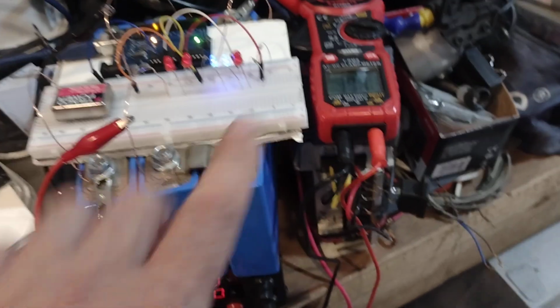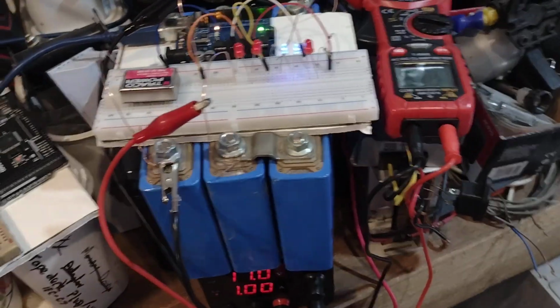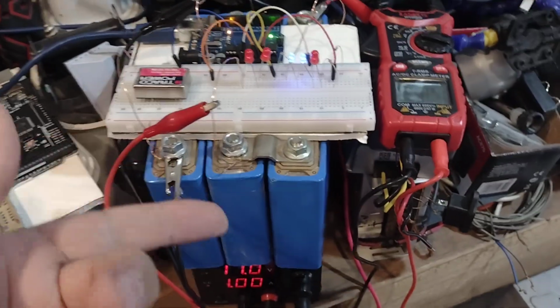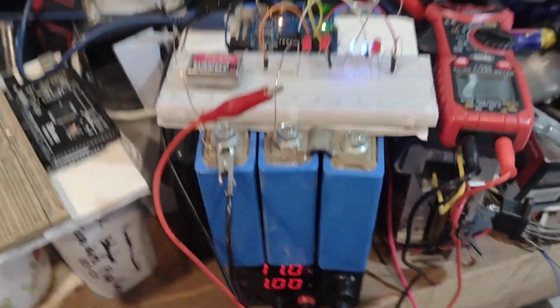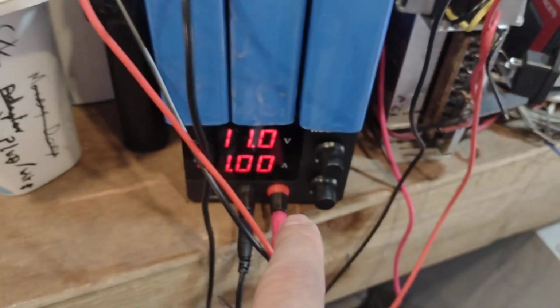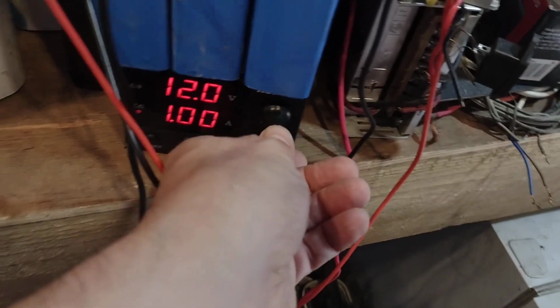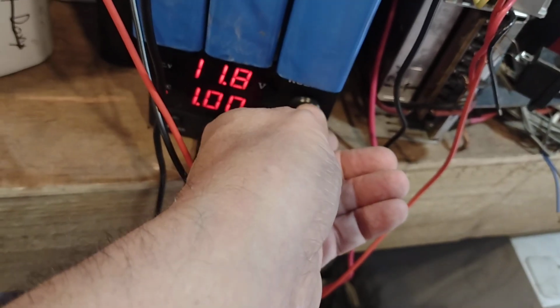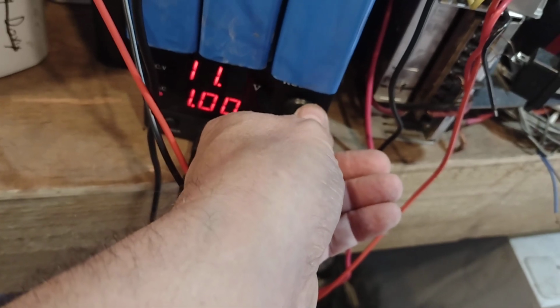What you're trying to get to is the point where they're all the same voltage, and I don't know what that voltage is. It depends on the voltage curve itself. It's not going to be 0.7, it's going to be more like 0.3 high. So this one's probably going to be something like 4.3, which means the voltage I'm setting is too high because it's going to cook it. So in order to make sure we don't damage the batteries, I'm going to take it down to 11.5.